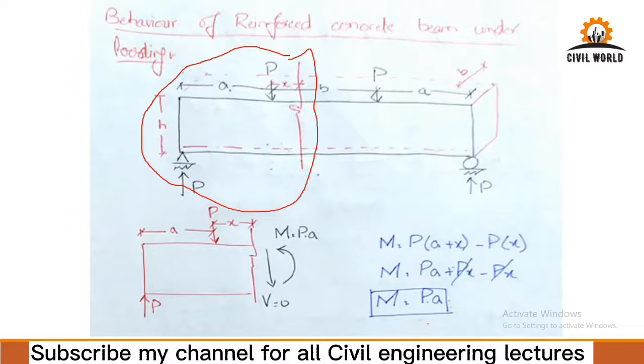Its solution is over here. It comes out to be P into A. You can take moment at this point, so this P is creating a clockwise moment at this point, which is P into (A plus X), and then this P is creating an anti-clockwise moment, which is P into X. So if you simplify it, it comes out to be P into A.